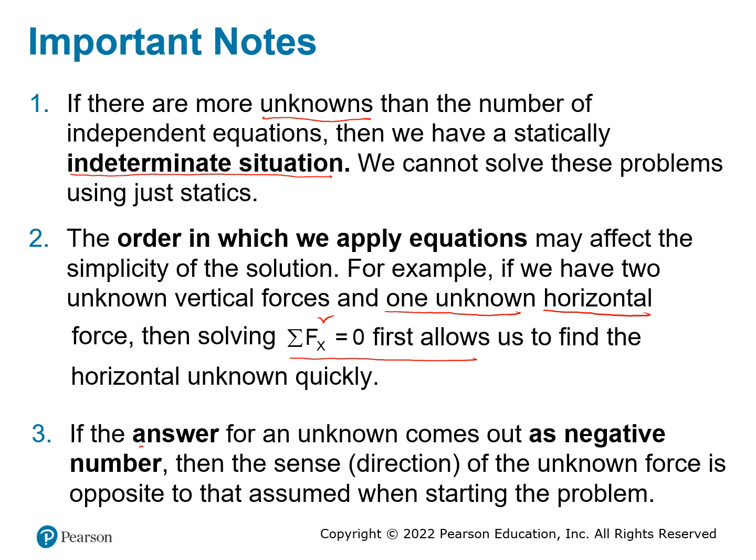And if you get an answer which is a negative value, that simply means that you assumed the direction of the force or the moment opposite to the actual direction. Then you just simply flip the direction in your picture. That's the correct direction of your solution.